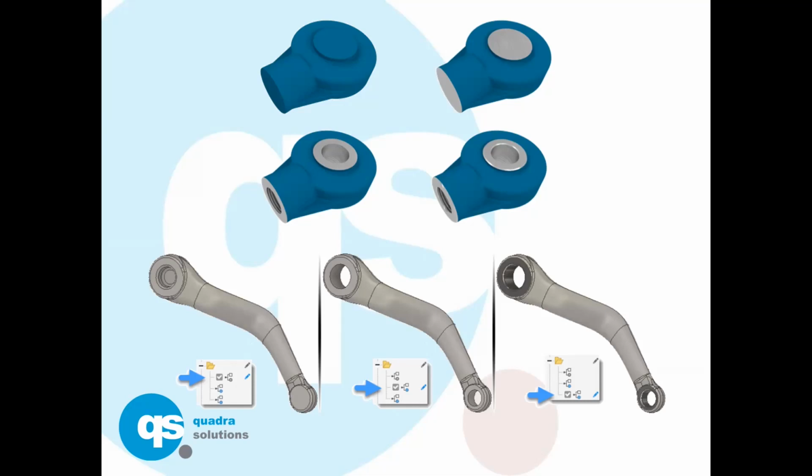By building this as a model state, the master file is the top left one, and then you add progressively, in this case, additional features. Some very thin extrusions, top right image there. That'll be for the machinist, for example. Exactly, a representation for the machinist, just flattening off subsurfaces. Then we take it over to the machine shop who then bore it out, do a bit of drilling and tapping. And the bottom right image, we've got some chamfers on there.